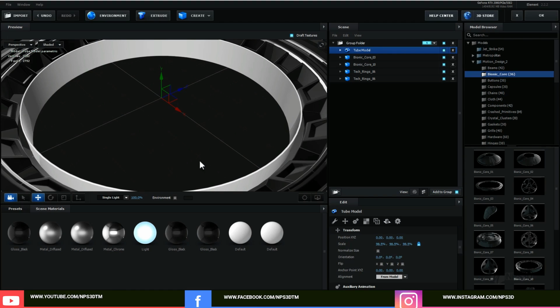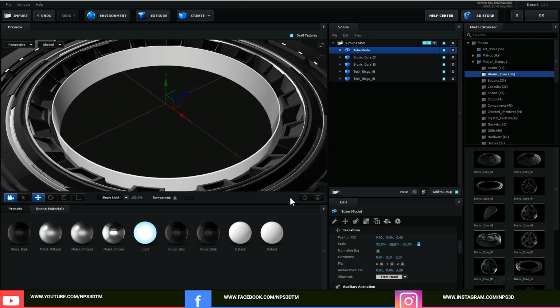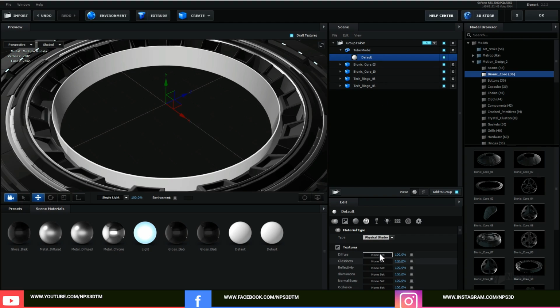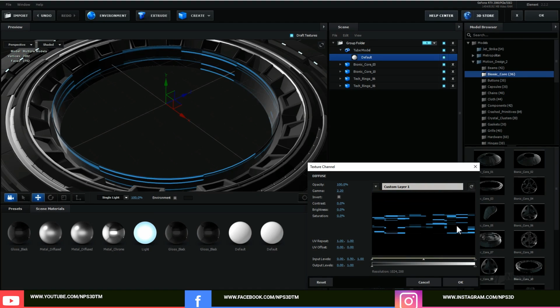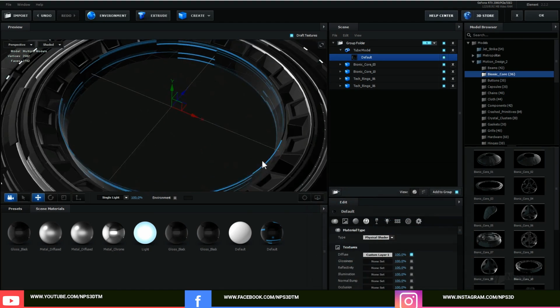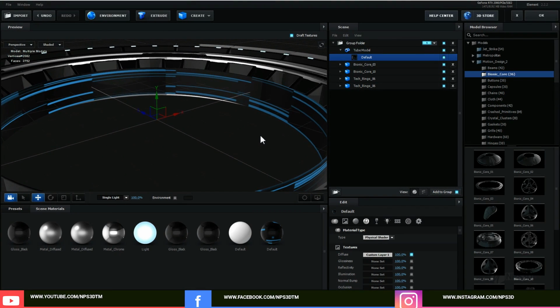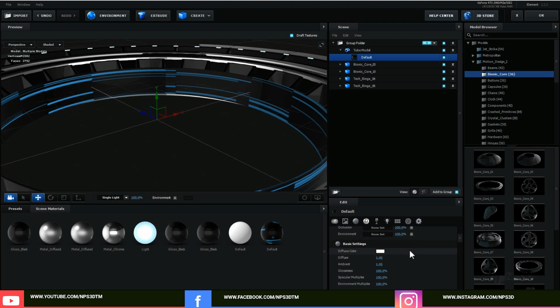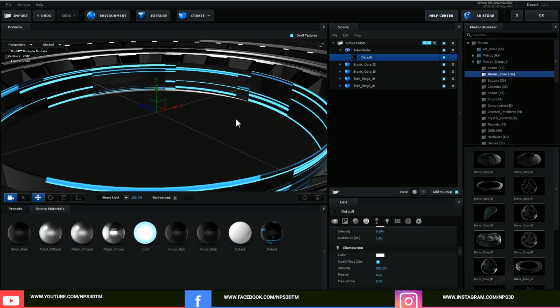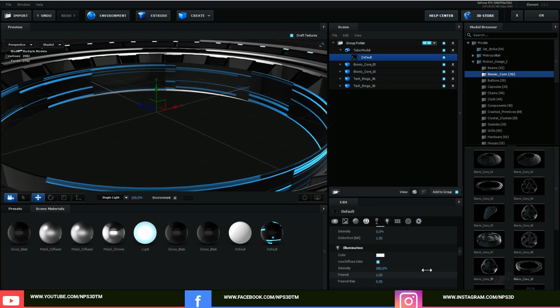So now let's go to the transform and just scale it a little bit down. You can also play with the radius, it works the same. Now let's select the material view and select the material and go to the diffuse section and load our material. This is the sci-fi lines, right? So now you can see it works the same, right? So go a little bit down and just go to the illumination and use diffuse color and increase it to make it a little bit brighter, right?